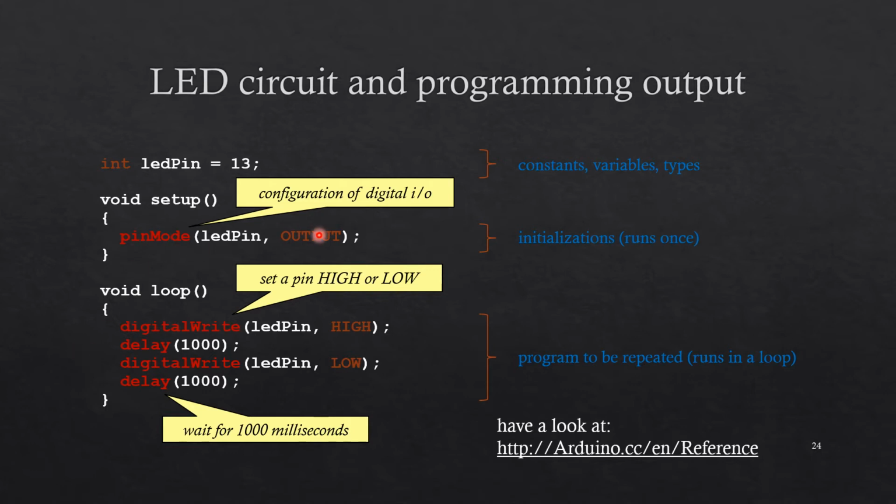So at this line, you can see that we are configuring the digital input and output by using pinMode, and pay attention to the capital and small letters. First, in the two parentheses we define what pin we are going to configure, and in the second part, separated by a comma, we say if that pin is going to be used as an output or as an input. You need to do this only once in the setup. And of course, semicolons at the end, because this uses semicolons unlike Python.